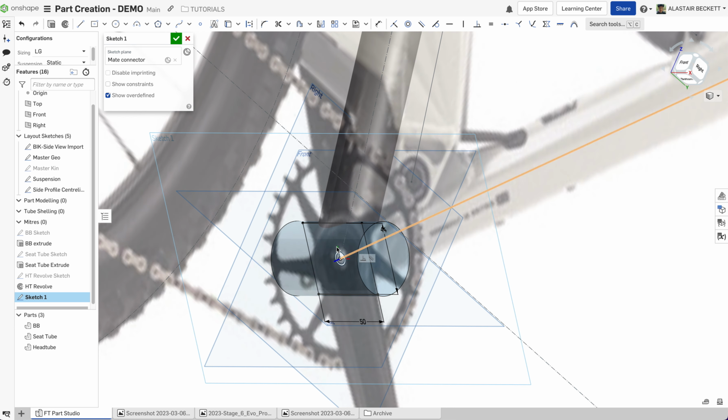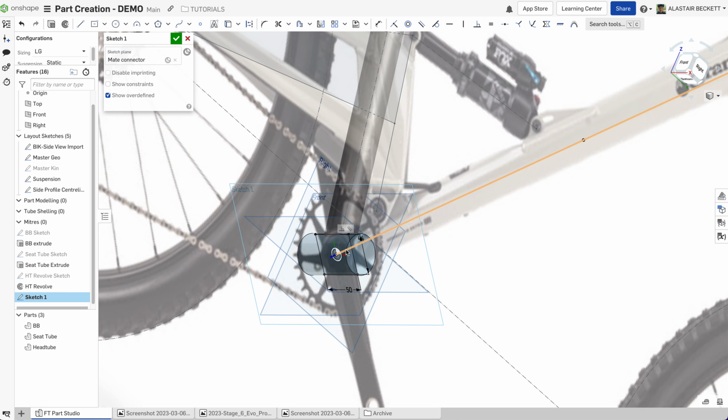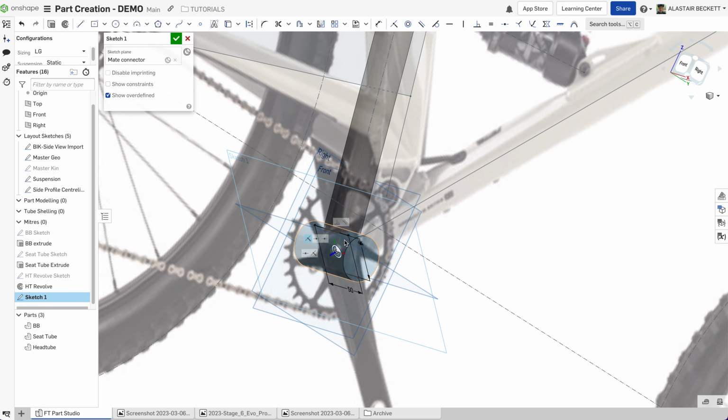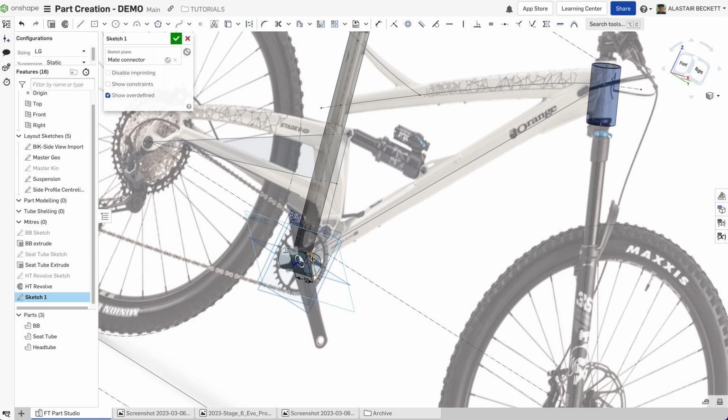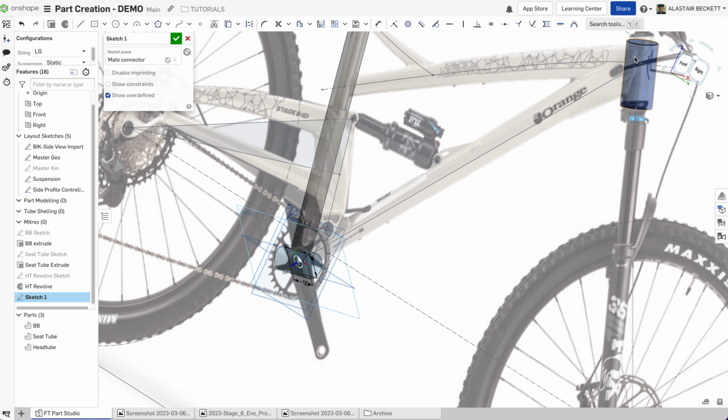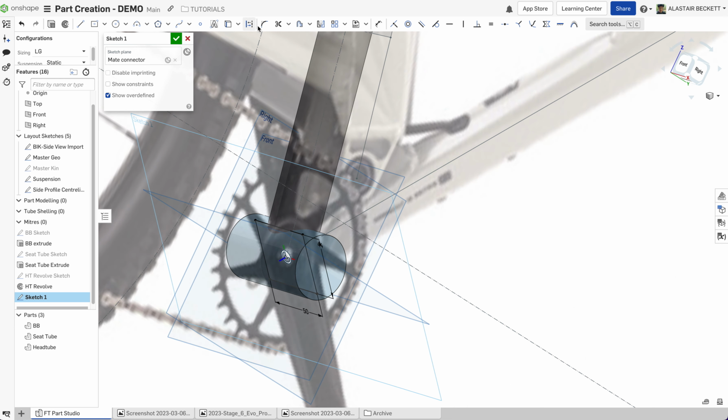Okay. So we could just extrude or loft this sketch, and it would basically be the same shape here as it is up here where it ends, but that's not what we want. That's just a normal extrude. So we're going to want to create a different profile up here, and essentially what the loft feature does is allow that to morph and transform from a square into a rectangle, whatever shape we put up there. But just to keep things a little bit more aesthetically pleasing, we'll put a couple of radii on the end here. So radius, we're going to say 7.5 on there. Okay, so that's our first sketch.